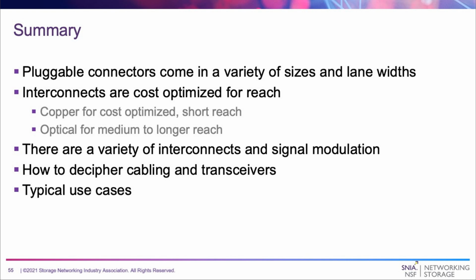It's on the order of less than 20 nanoseconds, and just about 1.5 watts per end. The DSP typically drew about 2.5 per end, so you'd have 5 watts for a cable. But it looks like the next generation is down in the 15 to 20 nanoseconds and 1.5 watts. So it's much more tolerable.